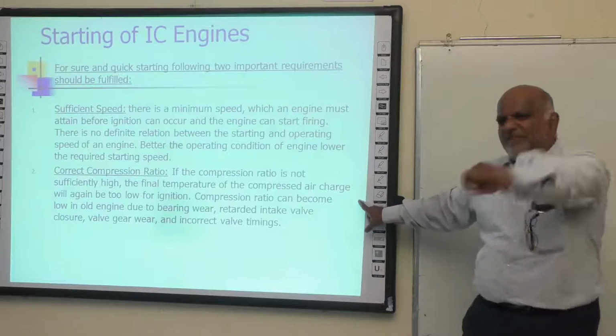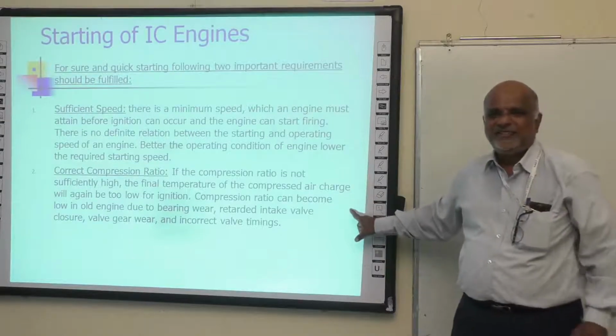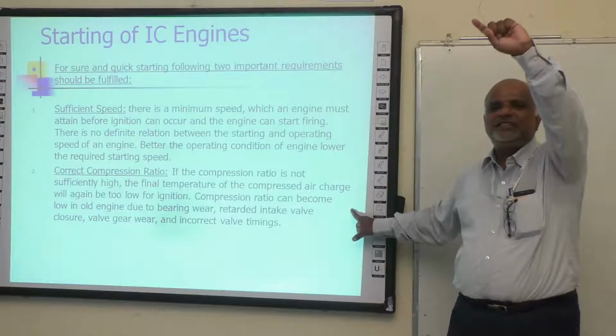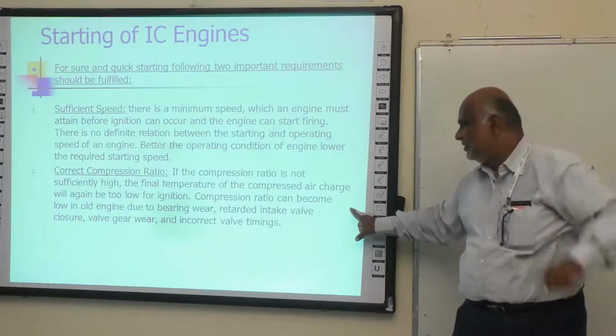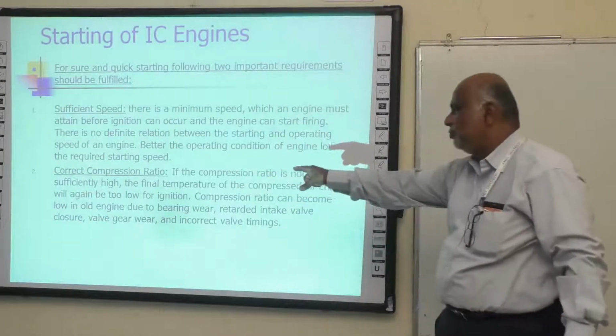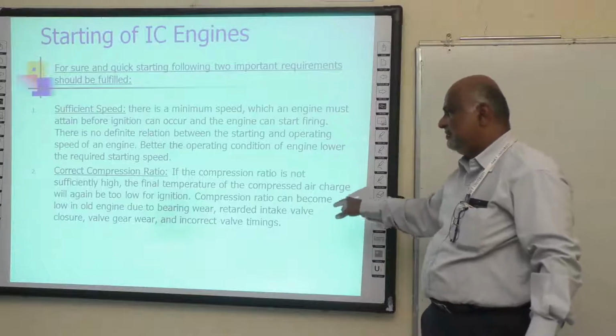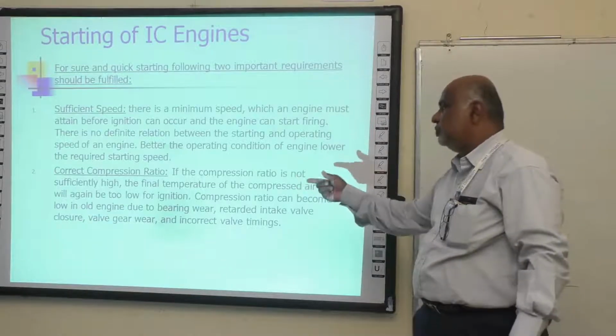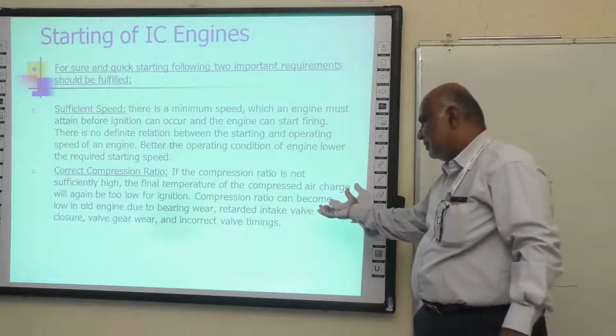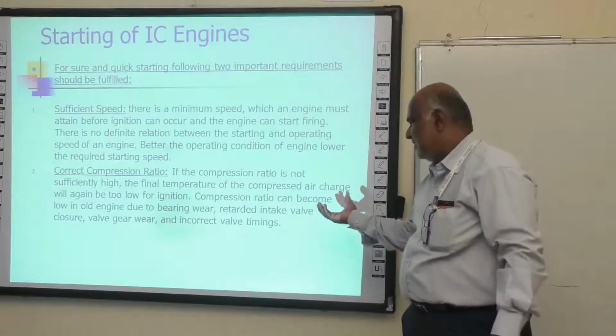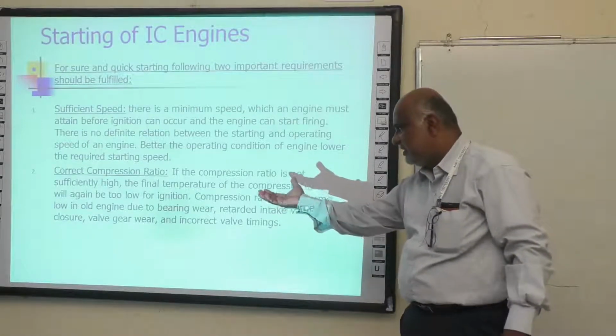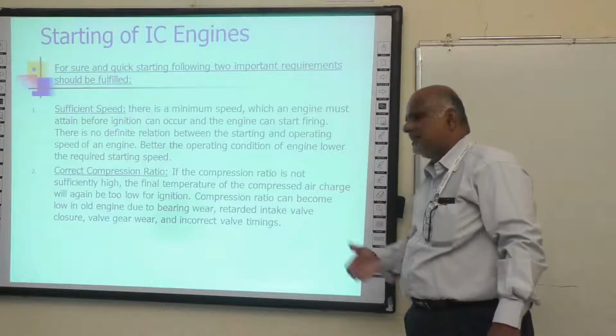The temperature of the air is what matters, because that air temperature should reach the spontaneous ignition temperature of the fuel. Compression ratio can become low in old engines due to bearing wear, barrel wear, and incorrect timings.